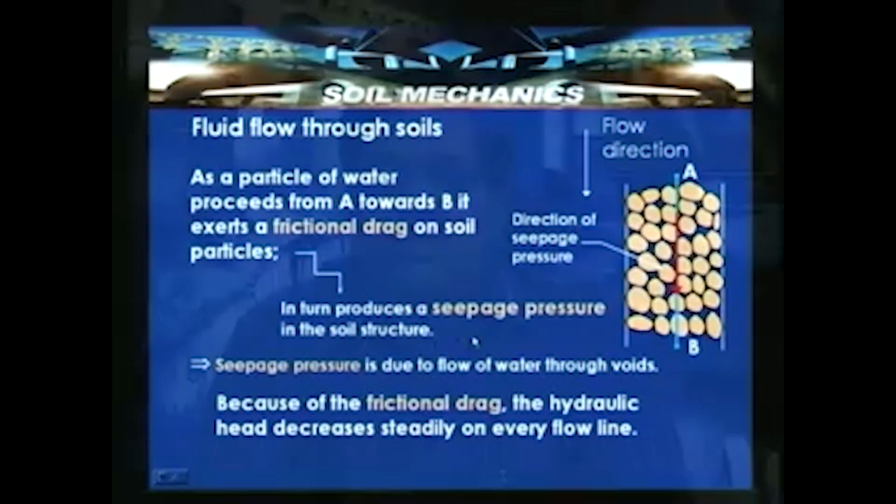That means this frictional drag, when it takes place, produces a seepage pressure which can induce changes in the effective stress. It depends upon the direction of the flow. If it is downward, then it can push the particles into denser packing positions. If it is in an upward direction, then the seepage pressure acts in the direction of the flow and can agitate the particles. That means the seepage pressure always acts in the direction of flow and can influence the effective stress, which we will be seeing very shortly.